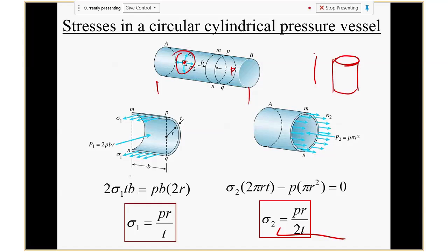All right, so last time we mainly talked about pressure vessels. And we actually use this a lot, because in our life you see around us there are a lot of pipes, can be gas pipe, oil pipe, any kind of pipe, always under pressure. And safety is a concern, so you basically need to find out what's the stress in the pipe to be able to design, make sure it's safe. Okay, so we end up with two simple equations for thin wall tube.